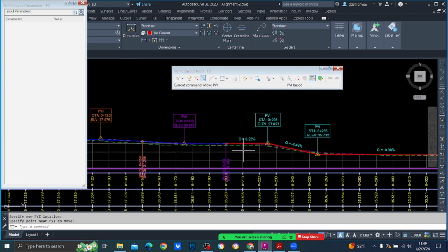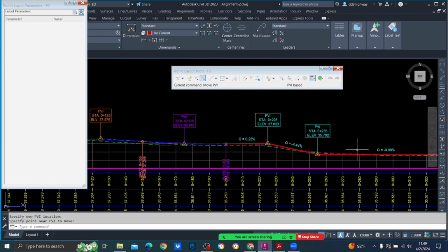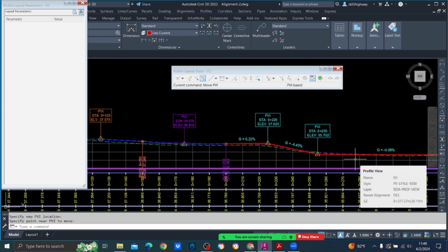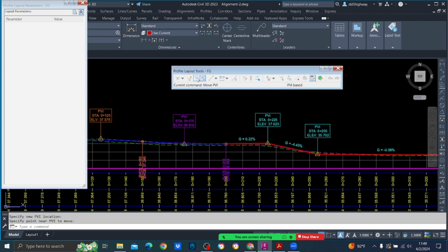But now the problem is you cannot have 250 curves here. Understand the problem? You cannot have 250 curves here. Then if you are going to reduce the curve length, you cannot maintain 50 kmph. So there is no other method that you can do. So it is 275.